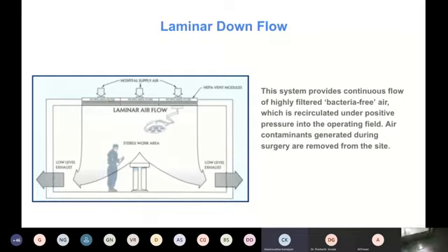We have a laminar flow station with a definite air changes per hour, and the air is taken back. It is not the case altogether. There should be a proper airflow pattern which has to be maintained, because the air has to sweep the particles across the peripheral areas. Then it has to be taken out.